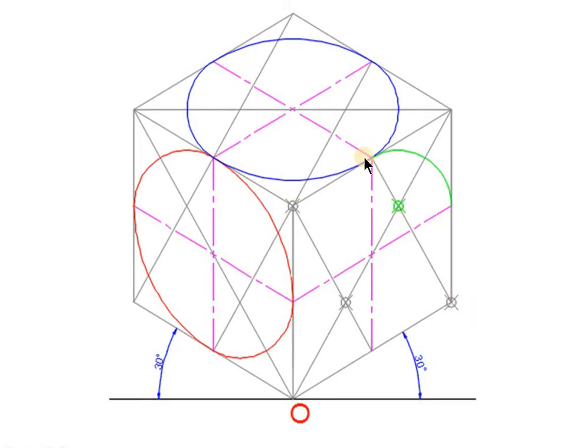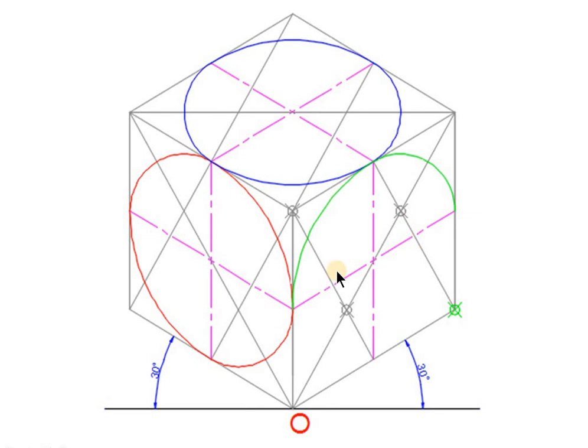So from this center you will draw this isometric circular curve, the quarter of this. Then from this center you are completing this. What you can observe here is that this is a semi-elliptical portion that we have completed. This is nothing but a semi-circular curve. One can see a semi-circular projection in orthographic views, and that is nothing but here it is semi-elliptical.